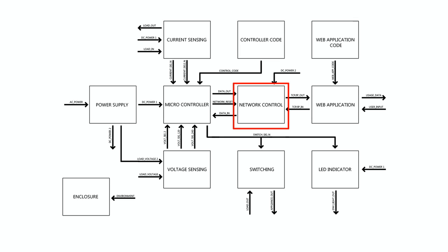The network controller sends and receives strings through UART to and from the microcontroller. The strings coming from the microcontroller contain power values, while the strings to the microcontroller contain commands to control solid-state relays. The network controller communicates directly with a web application via the internet, which is where previous and current power values are stored and displayed. The web application also stores a status that is changed by the user to determine if the attached appliances are supposed to be turned on or off.